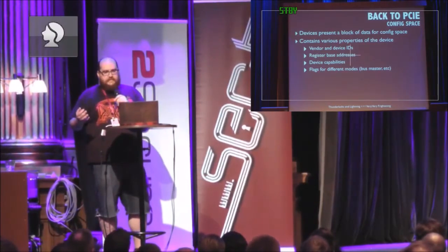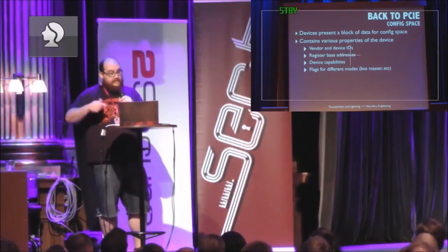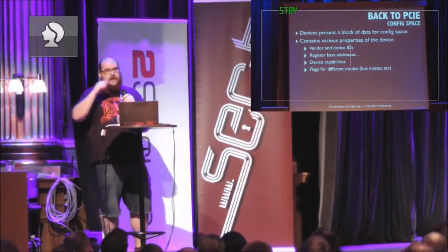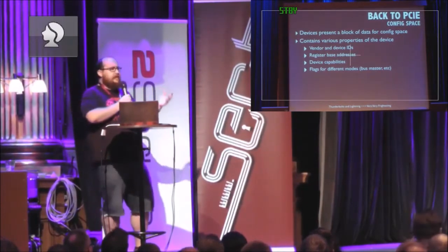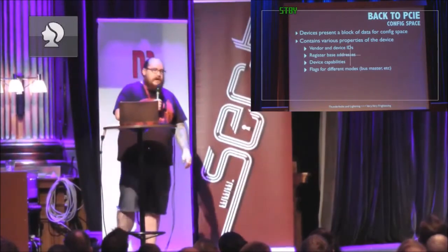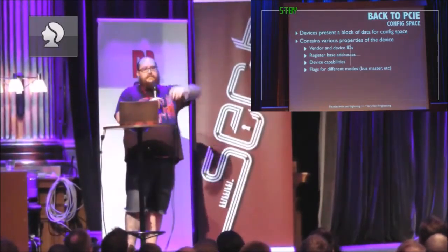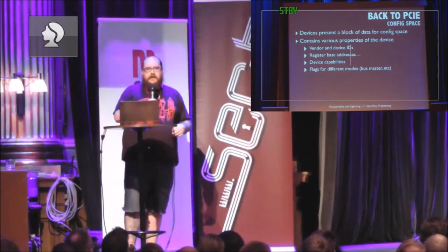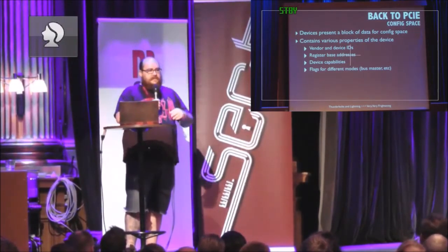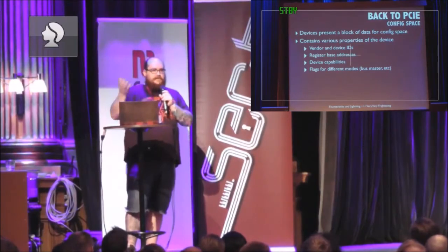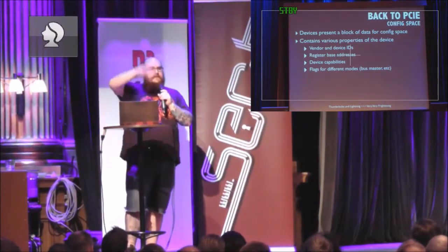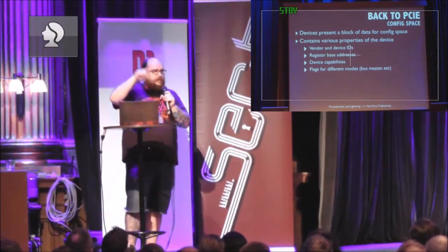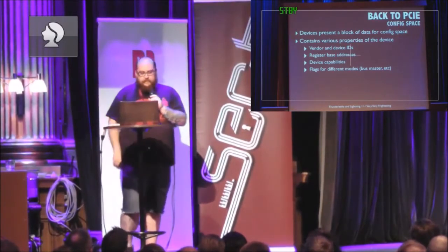There are base address registers that specify the base address for a DMA buffer that the system can just write stuff into, or a set of registers that are protocol specific. So say a SATA adapter will have a set of registers, and which one to write to is based on the SATA spec or whatever.